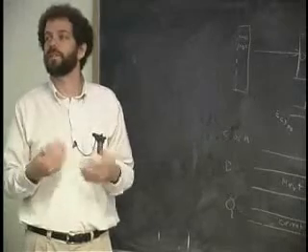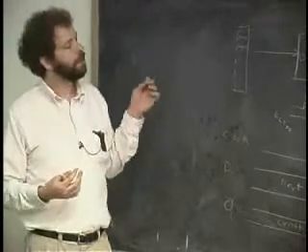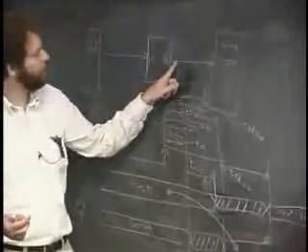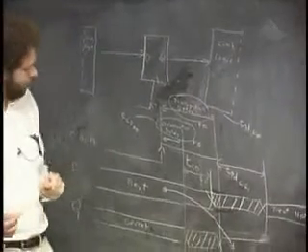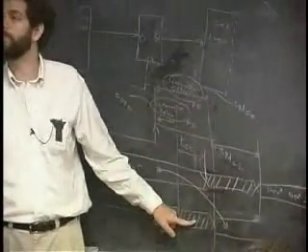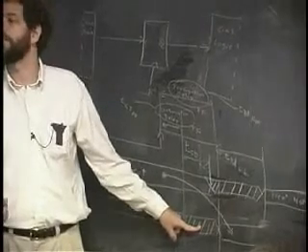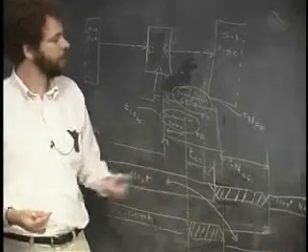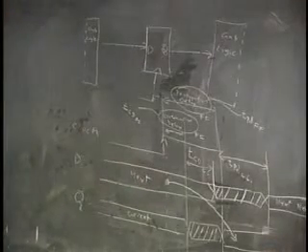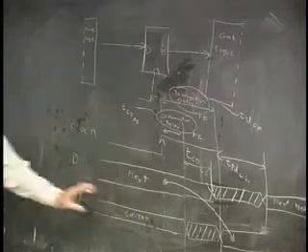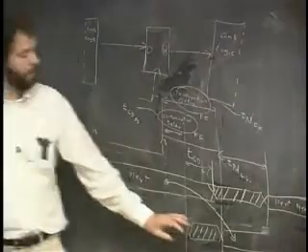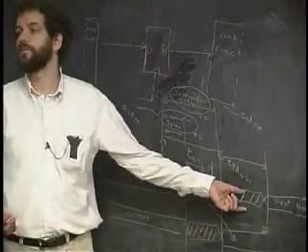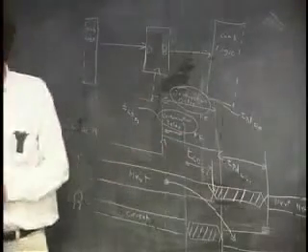All it has the power to do is to come out with an output. And so when there's contamination, when there's garbage, so what you're asking is, during this time, here's the Q value, there's garbage going into the CL. Why does the CL not go nuts and overheat and do bad things? And the answer is that the combinational logic is built in such a way that it can handle it. If the input is good over here, it generates good output over here. And if the input is garbage, it generates garbage. And that's just the way it works.